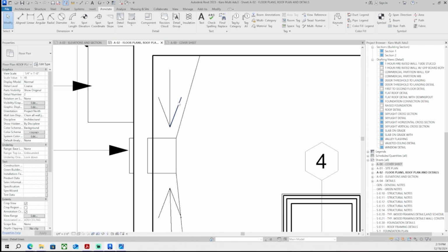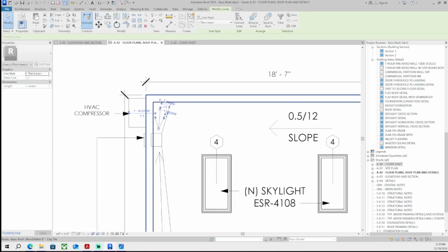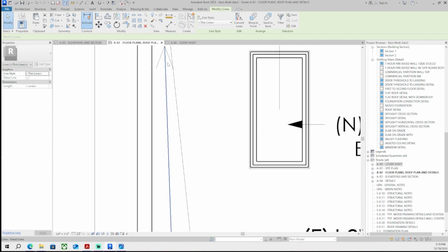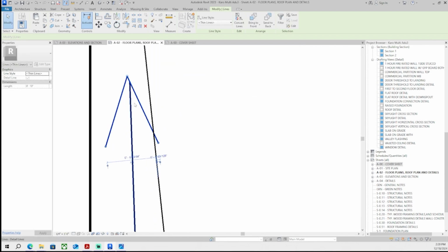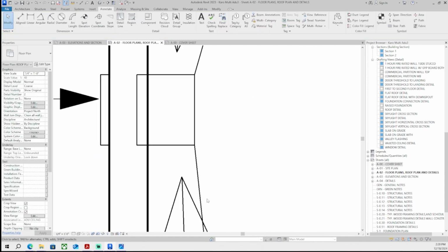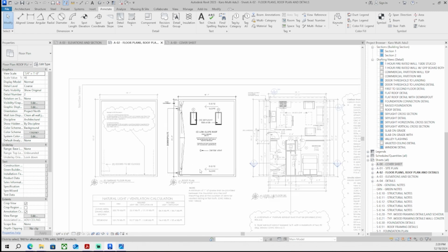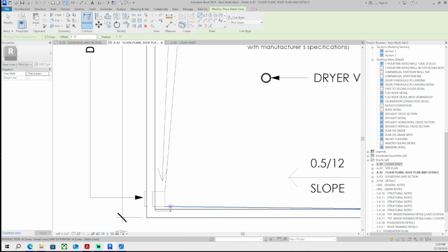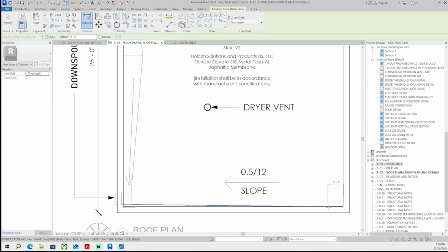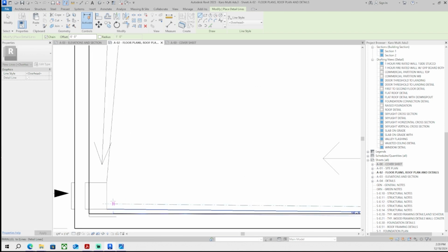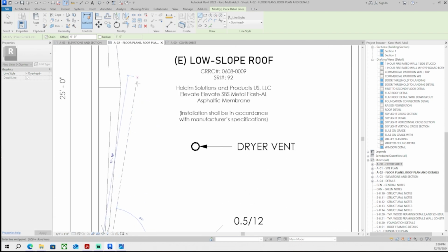So here we go. Here's the roof cricket, and you can start to visualize it. So you don't get ponding on the roof, so water doesn't collect. Because when you get ponding, that's going to be a point where it's going to leak from. No ponding on the roof, my friends. That's why on low slope roofs, which some people call flat roofs,